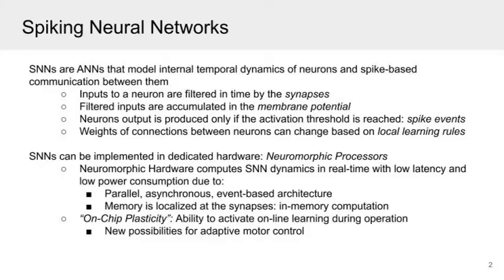Artificial neural networks are widely used in robotics, especially in computer vision but also in closed-loop control. Using large artificial neural networks comes with the need of a large amount of processing power. Spiking neural networks, on the other hand, are a type of artificial neurons much closer to the biological neurons. They accumulate input current and send out a spike whenever their internal variable, the membrane potential, reaches the threshold. Specialized hardware has been developed to simulate such spiking neurons with the goal of low latency and low power usage, while being able to scale to millions of neurons.